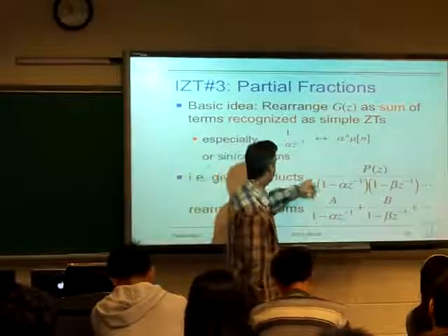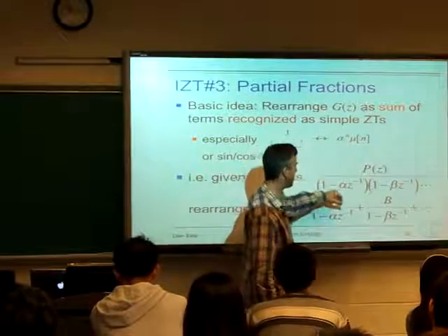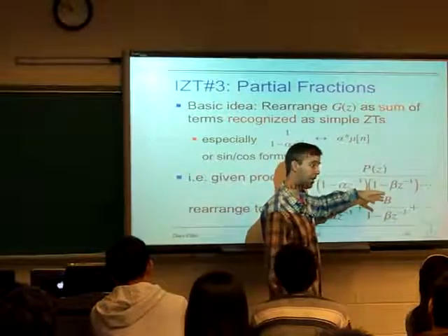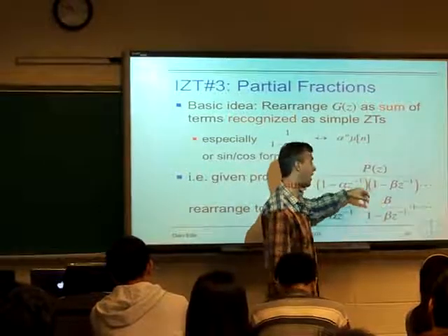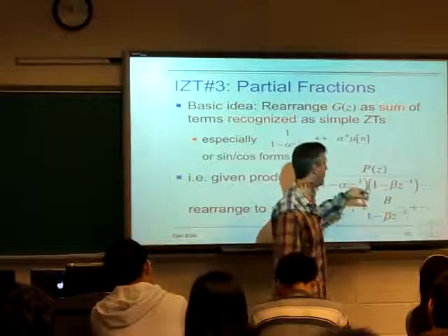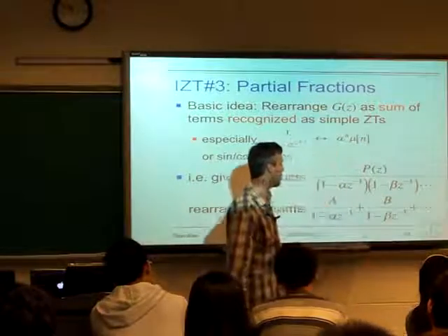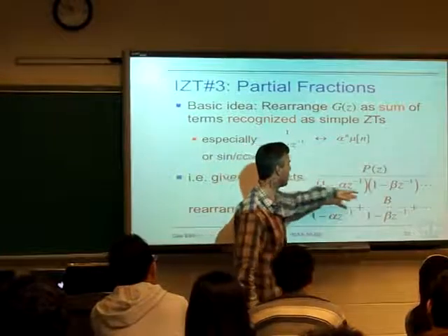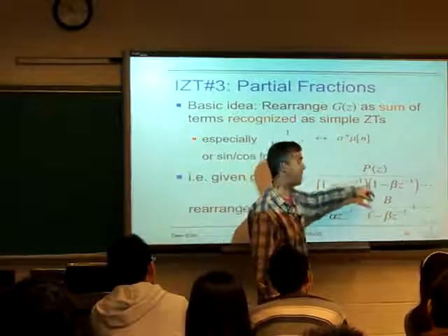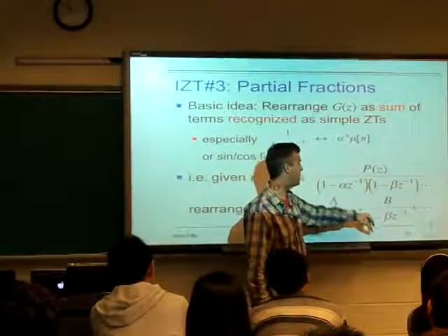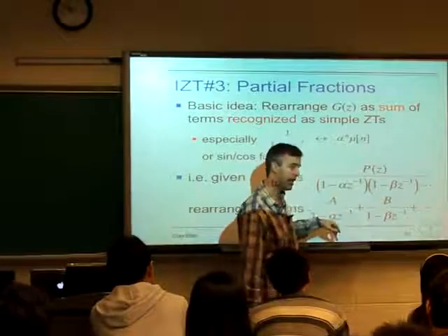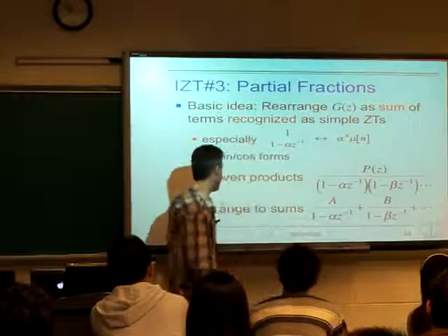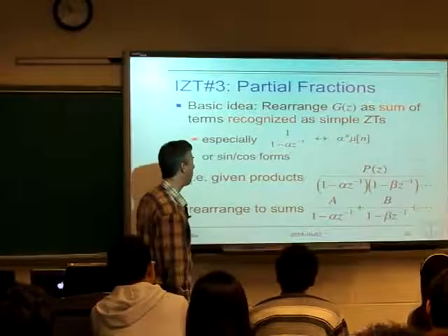Normally the Z transform we're given is expressed in terms of a denominator which is maybe a single polynomial in Z, which we can then think about factoring into a set of first-order expressions like this. But what we want is not a denominator that's a product of terms, but a set of discrete different denominators which are each individual first-order terms like this.